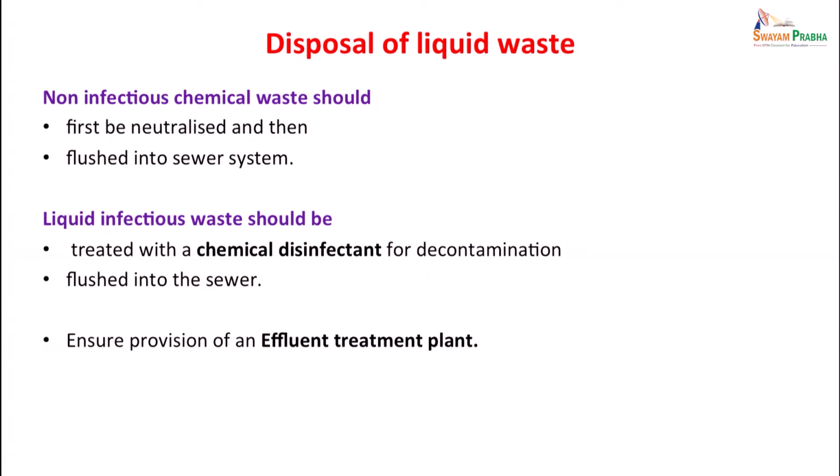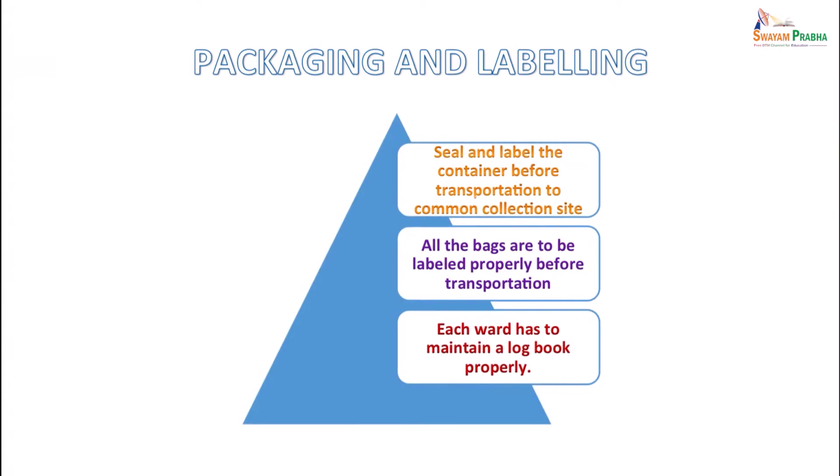As far as disposal of liquid waste is concerned, non-infectious chemical waste should first be neutralized and then flushed into the sewer system. Liquid infectious waste should be treated with chemical disinfectant for decontamination, then flushed into the sewer. And finally, there should be a provision of an effluent treatment plant through which the sewer transmission takes place.